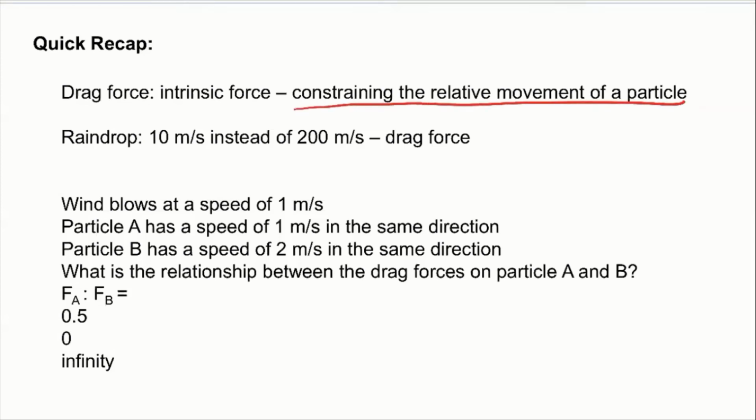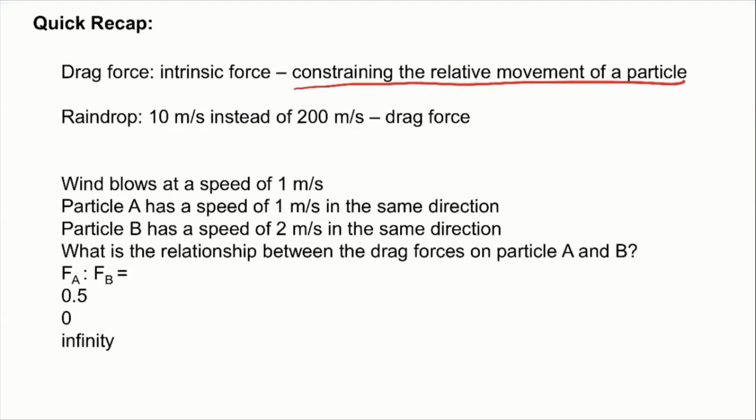Let's say if we have a very strong, very fast moving airflow, and you have slow moving particles, then that's going to exert a drag force on the particle so that it tries to minimize the relative movement of the flow and the particle. So also know that if there is no drag force, then the raindrop will fall with a speed of 200 meters per second instead of 10 meters per second. So that's why drag force is very important, right?